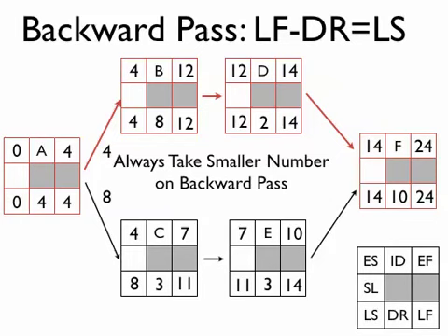So now we've completed both the forward and backward pass throughout our entire network. You want to make sure when you get back to A that your late start should be 0. In this particular example where we have one task that starts everything out, its early start was 0. We want to make sure when we go through this network and come back again that we're back at 0 for the late start. If you end up with 15 here or something like that, well, then you've done some math error along the way. You need to go back and do it again.